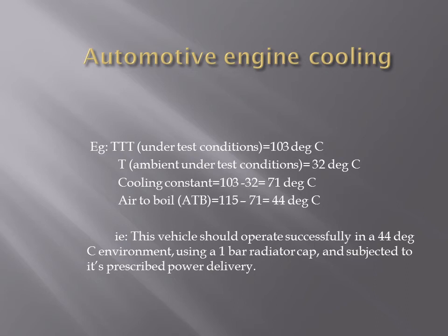The air to boil is the maximum allowable temperature of 115 degrees minus your cooling constant, 71, which gives you 44 degrees. That is, this vehicle should operate successfully in a 44 degree centigrade environment using a 1 bar radiator cap and subjected to its prescribed power delivery.